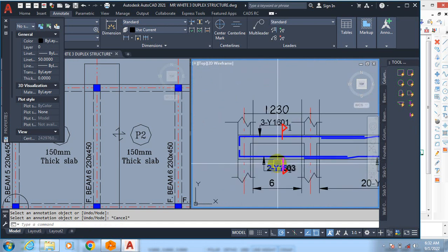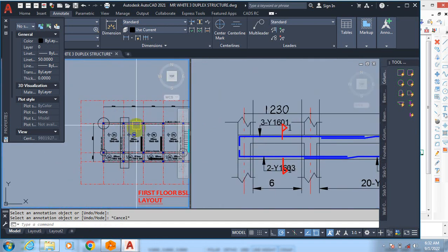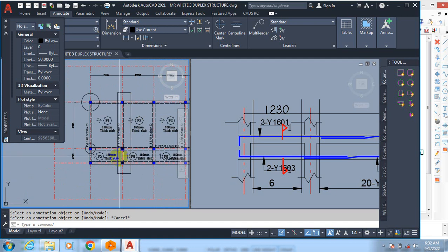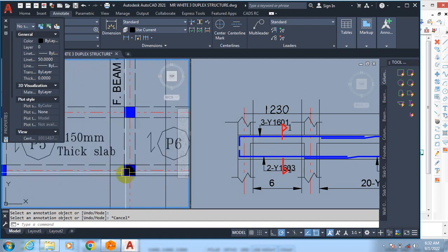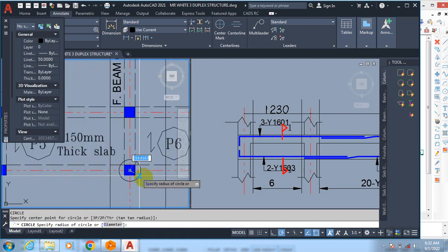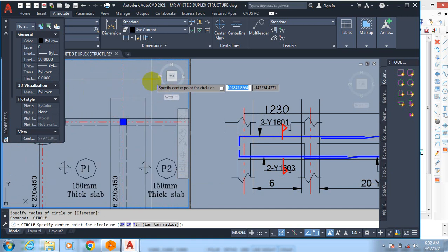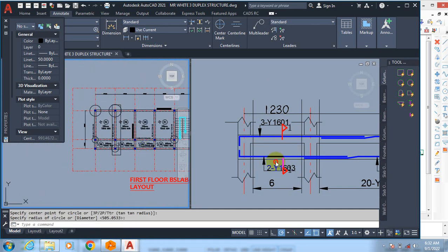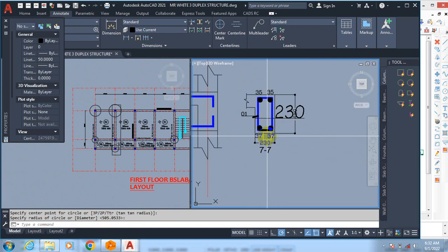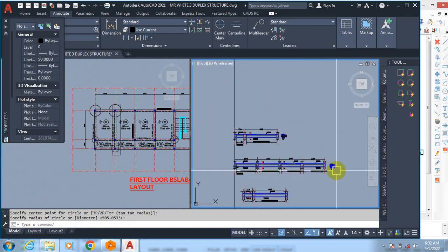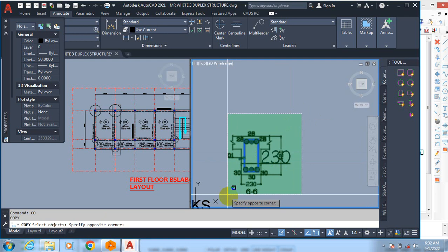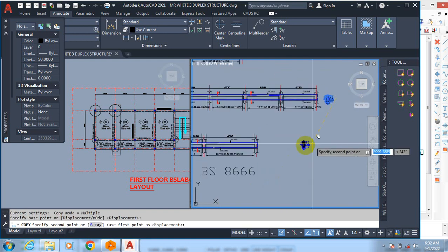And this beam, if you remember, I said by highlighting this beam on the general slab and beam layout, you are going to see that around this area we have a T shape. Around here we also have another T shape. So this is actually a T-beam. In that case, our cross section is supposed to come in the form of a T. So all I need to do is pick this T shape.